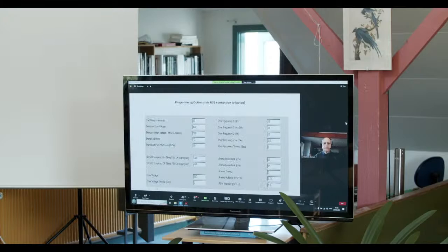Okay, these are some of the screens on our controller software, the options that you have available. You have the histories, the pulse width modulated dump load. In this case, the dump load would start at 400 volts with 0 power, pulling 100% of the load at 500 volts. So you might have a power curve that's operating up to, say, 360 volts, and at 400 volts, the dump load would gradually come in. At 500 volts, the dump load would be applied 100%.